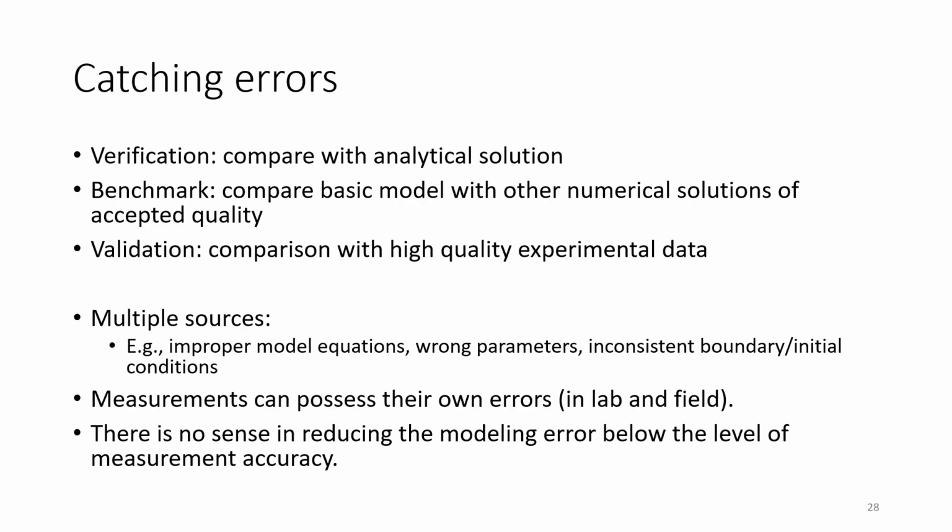How can we quantify and catch those kinds of errors? I already named a few at the beginning of this course: verification, validation, benchmark, where you compare different numerical codes with each other. All those are possibilities to quantify your discretization error, to get an idea about the accuracy of your model.